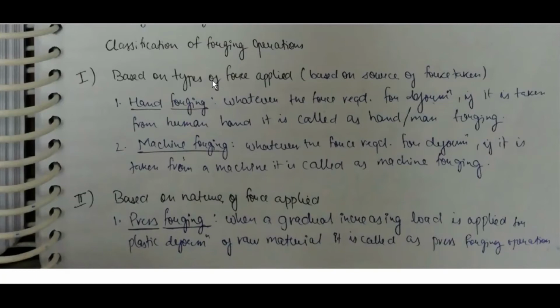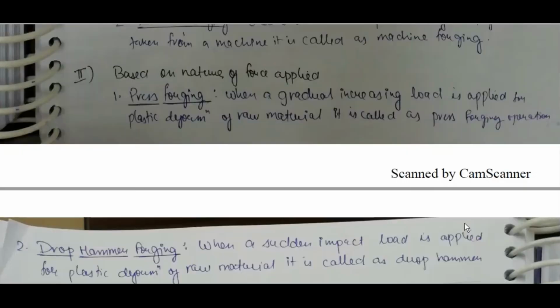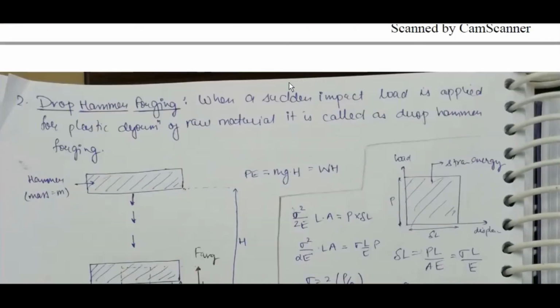Therefore, the material simply expands and produces a barrel-shaped component. As the material simply sticks to the die surface, it is called the sticking friction model. On continuous downward movement of the top die, the expansion force keeps on increasing, and at one point the expansion force